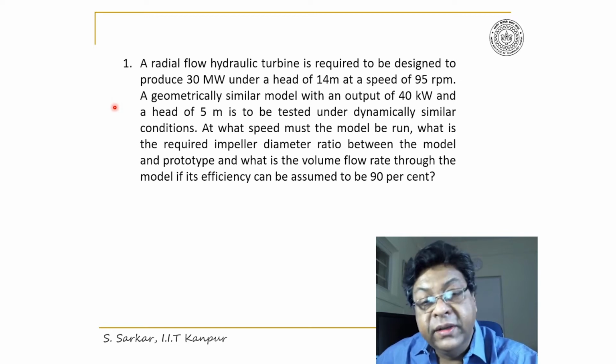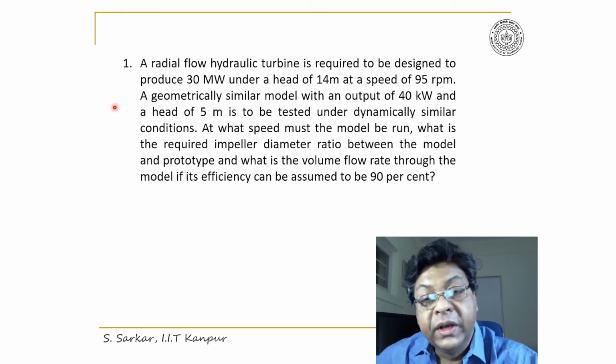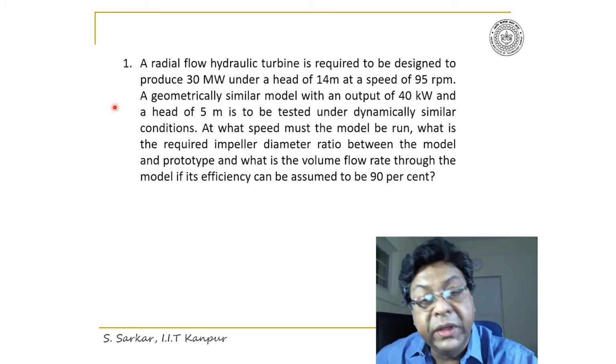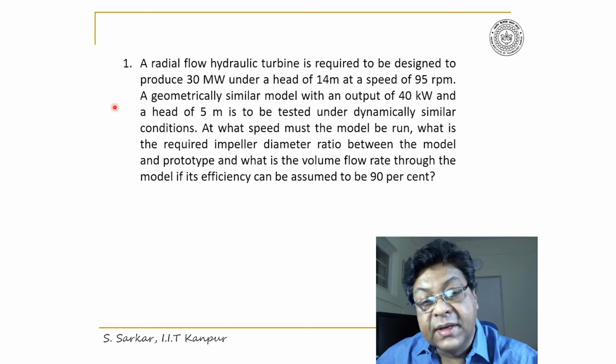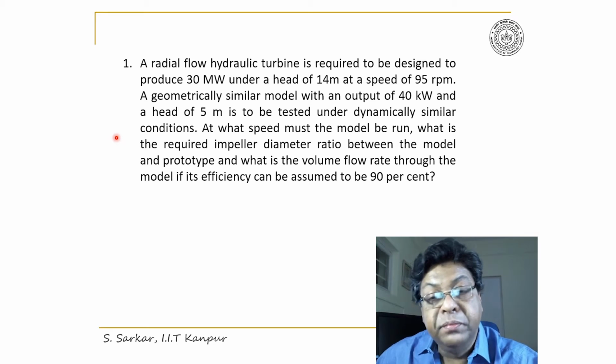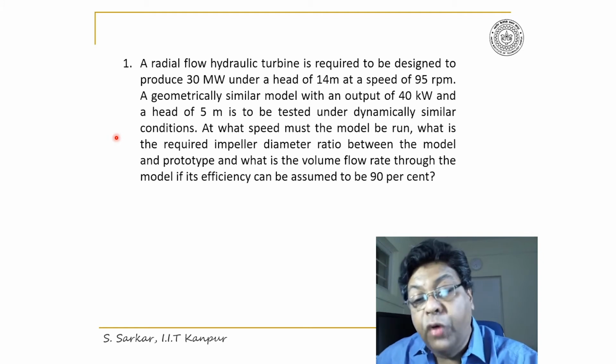A geometrically similar model with an output of 40 kilowatt and a head of 5 meter is to be tested under dynamically similar conditions. At what speed must the model be run, what is the required impeller diameter ratio between the model and the prototype, and what is the volume flow rate through the model if the efficiency can be assumed to be 90%.